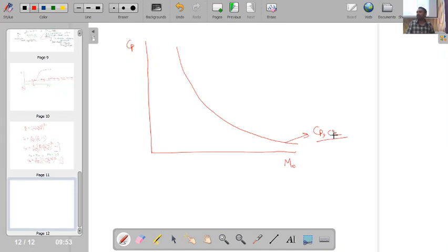So this is my Cp critical solution. And for the subsonic flow situation, just now we have seen from the Prandtl-Glauert rule or any other rule, like the Karman-Tsien rule, if we calculate the value of Cp, that varies something like this with Mach number. So this is coming from the Prandtl linearized pressure coefficient.